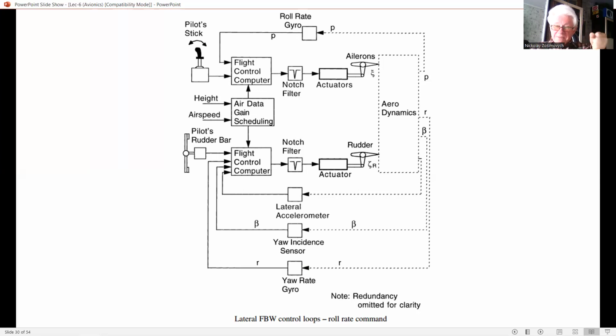Consider now the pilot as part of a closed-loop control system. There are many lag elements in the outer control loop, comprising the pilot and the FCS or airframe combination, and the phase lag around the loop reaches and exceeds 180 degrees as the frequency is increased.